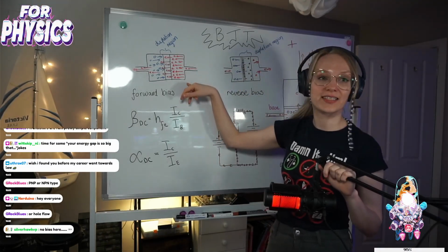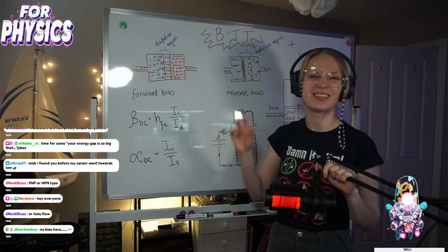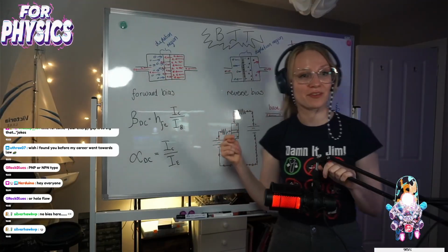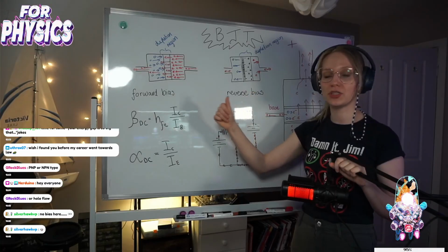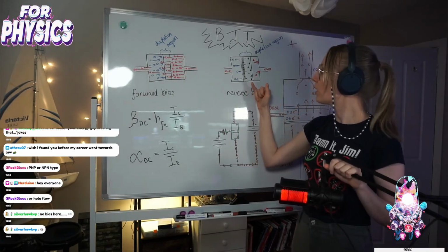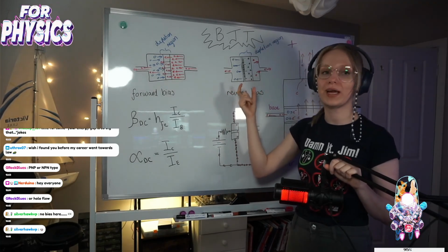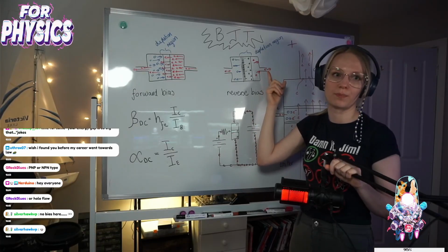So forward bias is like, yay, once you reach 0.7 volts, the electrons can jump over the barrier. It's not even jump over. The barrier gets smaller and electrons have an easier time getting through. In a reverse bias situation, if you're putting the current in the opposite direction, what happens? The depletion region actually quite literally gets bigger. There is no way electrons will flow. A couple of electrons will move because you've set up a positive voltage.